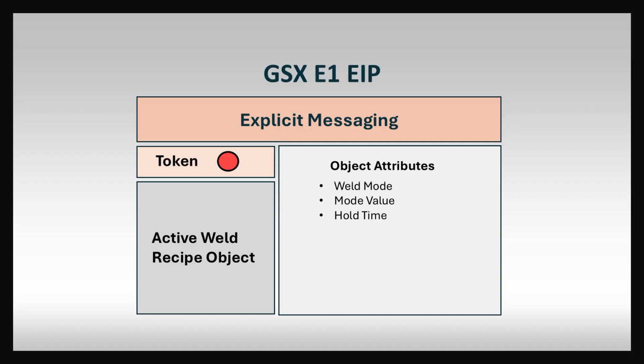Hold time, sets the hold time duration. Trigger force, specifies the force required to trigger ultrasonics. Amplitude, sets the ultrasonic vibration amplitude as a percentage. Weld force, defines the actuator force applied during ultrasonics. Hold force, defines the actuator force applied during the hold phase.